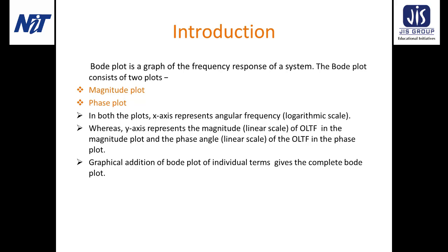For the magnitude plot the y-axis represents the magnitude in the linear scale, and it is also in dB, and for the phase plot the y-axis represents the phase angle in degrees. And if we add the different parts of individual terms, it will give the complete Bode plot.